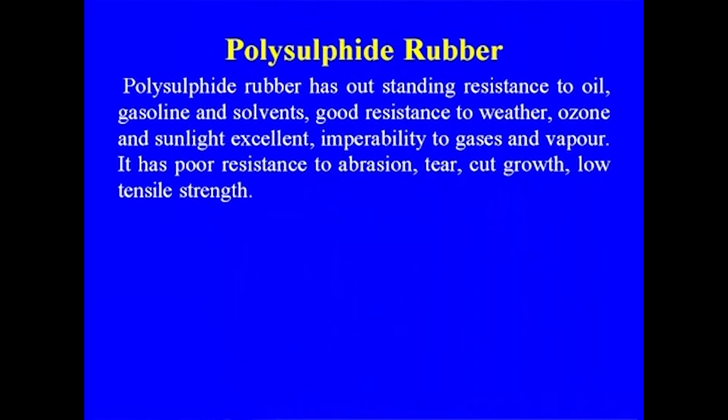Polysulfide rubber. Polysulfide rubber has outstanding resistance to oil, gasoline and solvent, good resistance to weather, ozone and sunlight, excellent impermeability to gases and vapor. It has poor resistance to abrasion, tear, cut growth and low tensile strength.